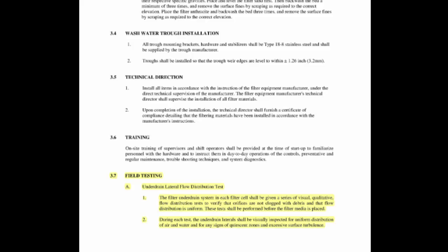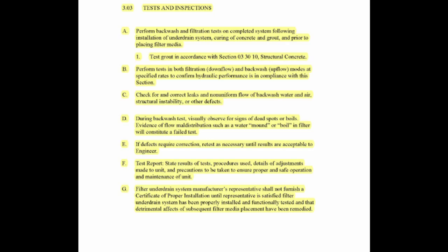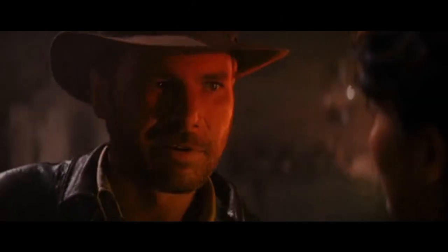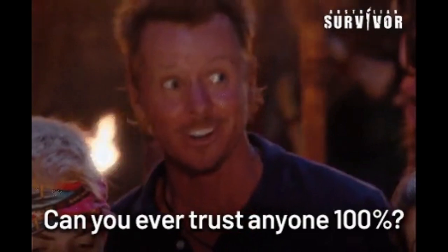Post-installation testing of gravity filters is extremely important to verify structural strength and to validate proper distribution. All too often in the filter specifications, paragraph 3 has minimal, vague, or insufficient testing to prove that the filters will actually perform as they're supposed to. I've repeatedly seen owners and engineers delegate solely to the manufacturer whether the filters operate properly. With no objective testing criteria other than the manufacturer's opinion, that's clearly a conflict and certainly not in the best